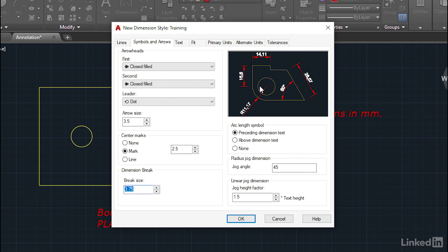Now the preview's obviously not got that much magnification on it, so you can't really see it, but you can also go and set it to lines as well if you want to. Personally, I leave that set to none because those marks and lines just create more objects that you'll probably have to delete at some point when you move the circle or change the circle or whatever. So I set that to none because the dimension will still pick up on the circle or the arc anyway.